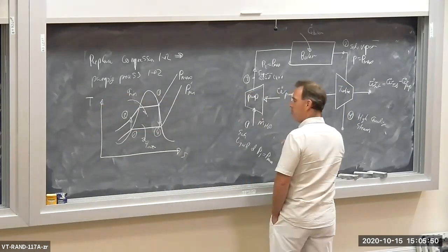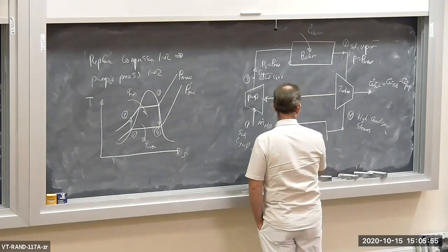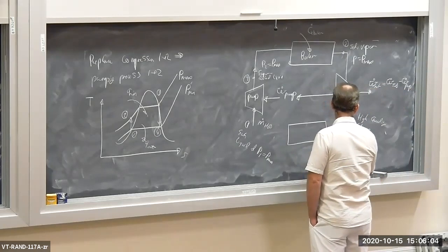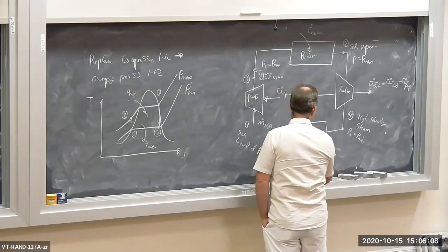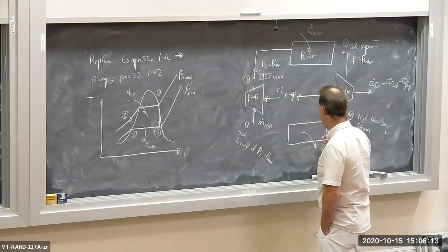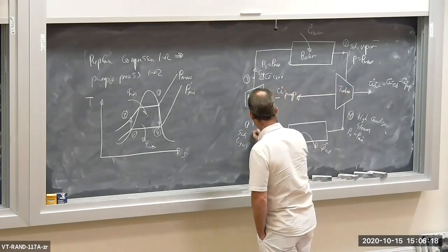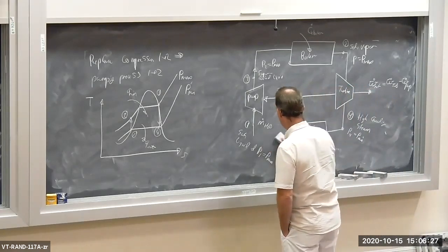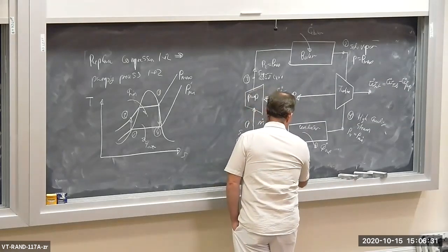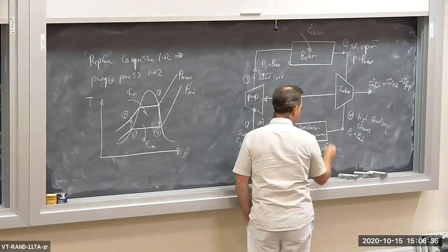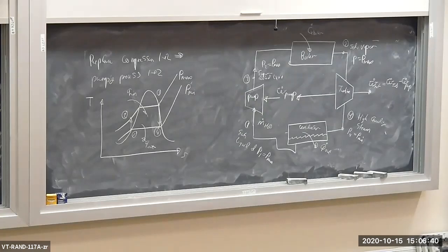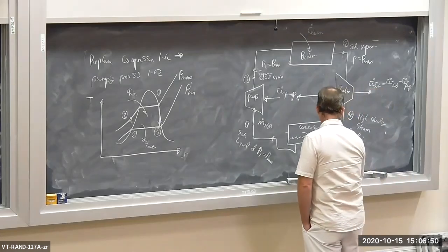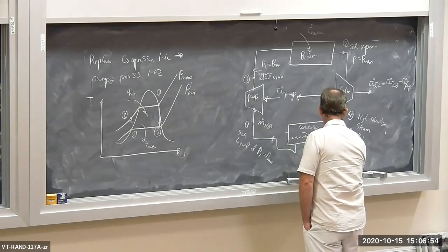Okay, now we got to get rid of the excess heat to complete the cycle. We pass the saturated mixture, high quality steam, at low pressure. By the way, P4 is back down to P min. And we reject the heat, Q dot out, and the Q dot out occurs in a condenser. We take a vapor and we condense it to a saturated liquid. So this is called a condenser. If you want to know how this physically works, basically, steam comes in, heat gets rejected, and we get liquid saturated at the very bottom of the condenser. And that gets pumped back to the pump. Okay, that makes its way back to the pump. So this Q dot out is Q dot condenser.